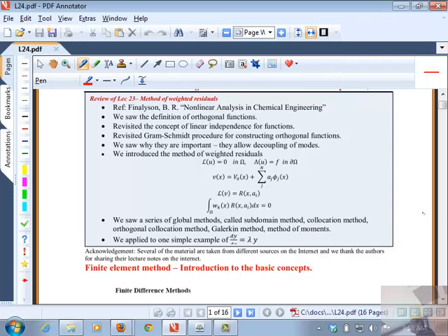If you're given a matrix, you find its eigenvectors and pre-multiply and post-multiply by the eigenvector transpose of it, you diagonalize that. So you decouple the variables. Another way of saying that is the modes are decoupled. Each eigenmode does not influence the other. So you have an uncoupled set of equations.